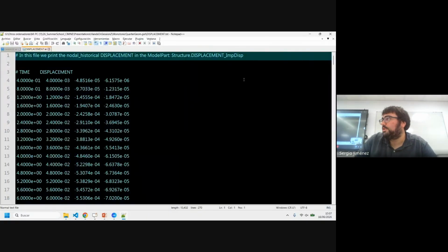Saying this because usually when you are preparing a simulation, the first time that you run the model will not work. So instead of waiting until this finishes, going into the model, selecting the point, going to Excel, seeing the results, this is just generating a file which is being updated from step to step, copying the data and going to Excel, and that's it. So you can easily control the evolution of that parameter.